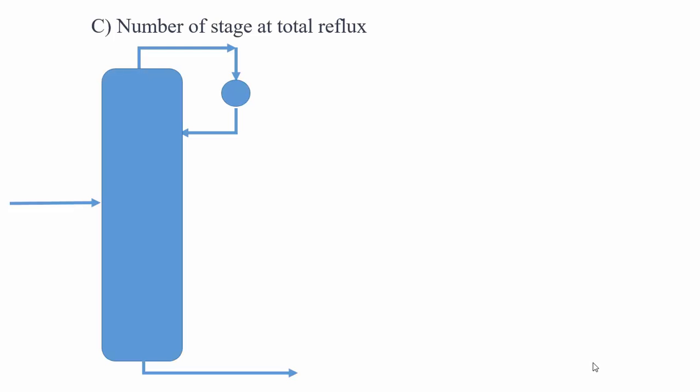So first of all, you have to know what total reflux means. When you say total reflux, it literally means totally refluxed. From the top, there is no product collected. That means all the condensed vapor will be sent back to the column.